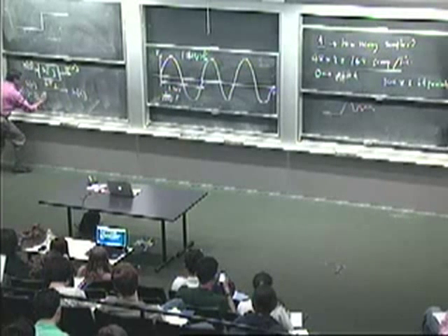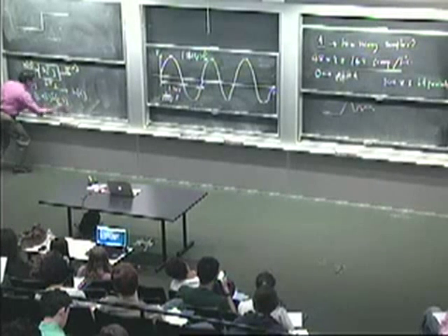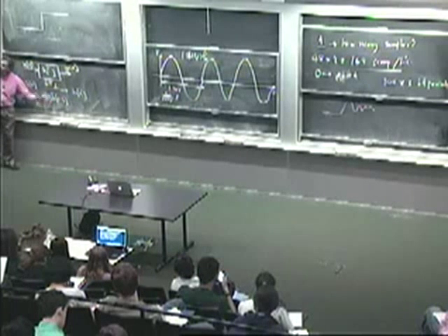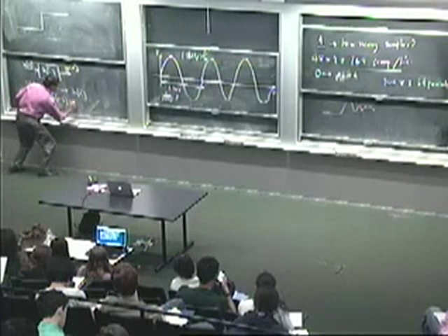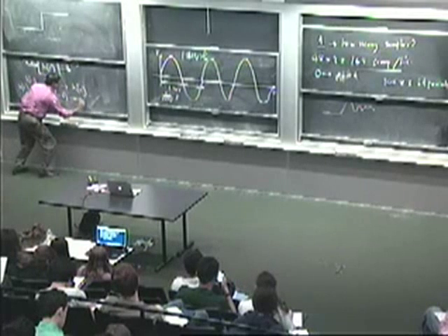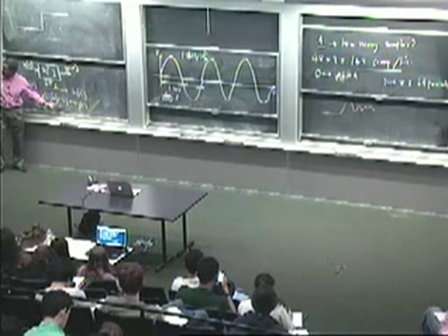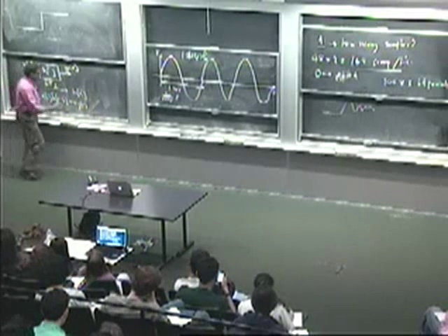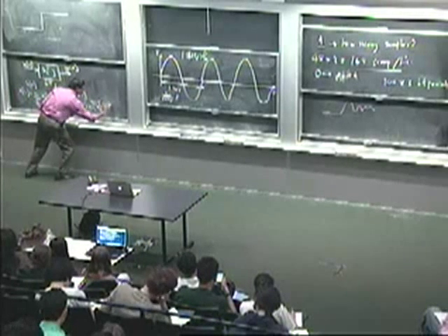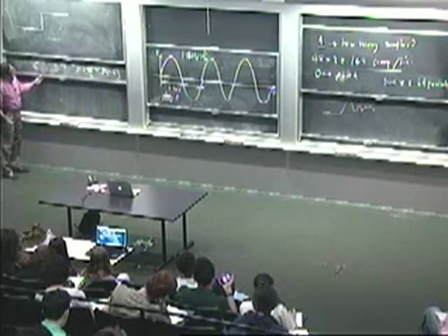Let's say x[k] delta of n minus k summed over all k, right? That's a general input represented as a weighted combination of unit samples. Well, what comes out in that case? What is y of n? If we're talking about a linear time invariant system, then it's the same weighted combination of the responses to these unit samples. So we're going to get summation x[k] h of n minus k, right? So this is the convolution expression that we talked about last time.